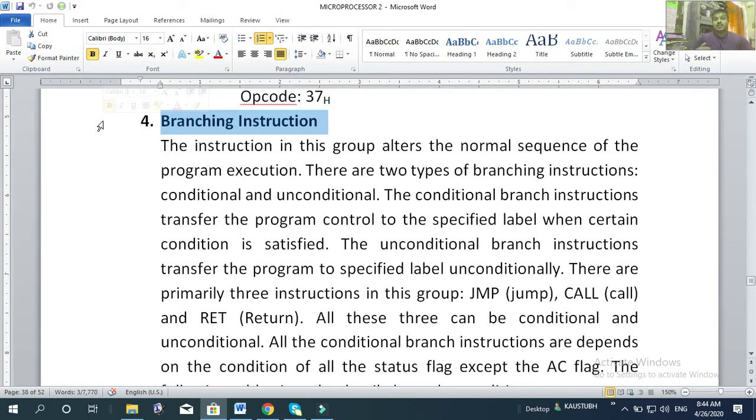Then forcefully, by means of some instruction, I have to enter the address of instruction 5 into the program counter. Because normally it does so automatically. The program counter is incremented by 1 after executing each instruction. So while I am trying to alter, forcefully I have to enter the address to which it would like to alter into the program counter.